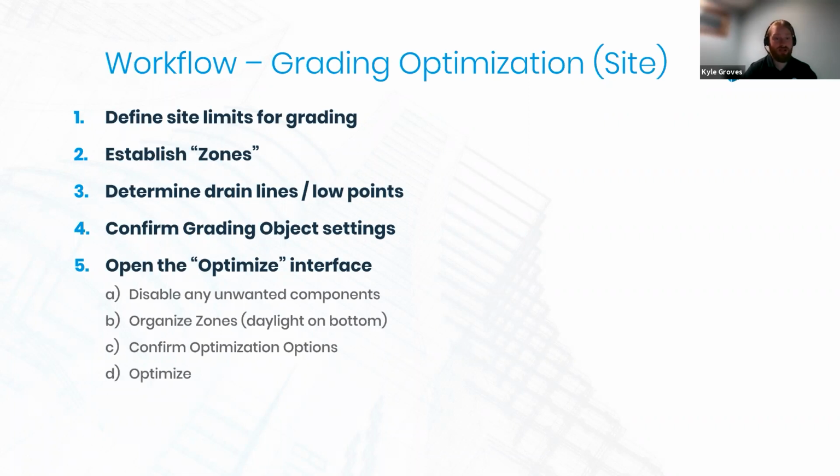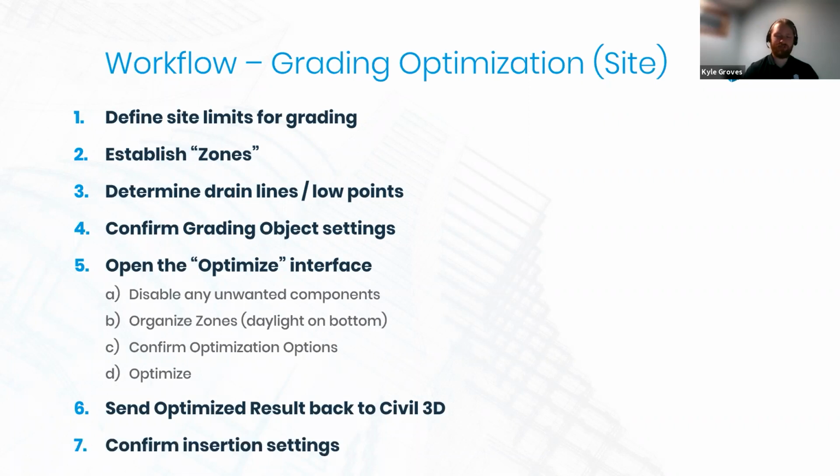And then you're going to run through and optimize, but you're not done there. This is a separate piece of software. So it's going to have to send that data back to Civil 3D. It'll do that through a LandXML. And then you're just going to confirm how you want that to get inserted inside your drawing. Let's go ahead and check that out.